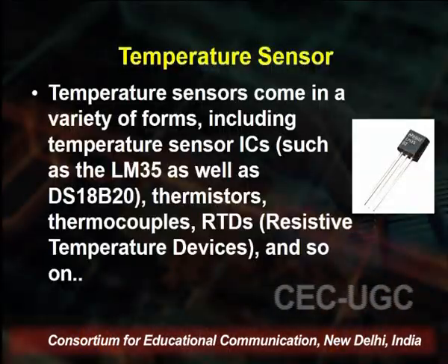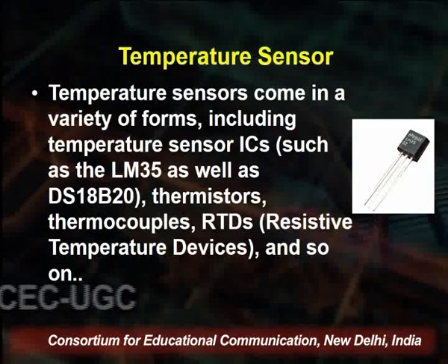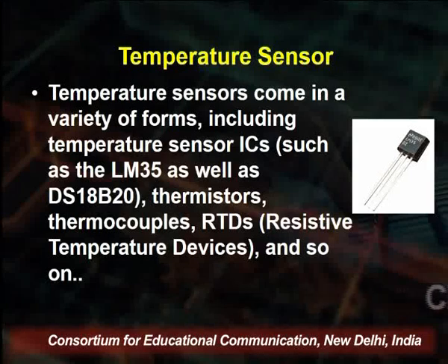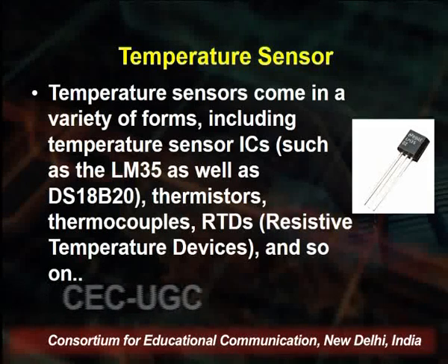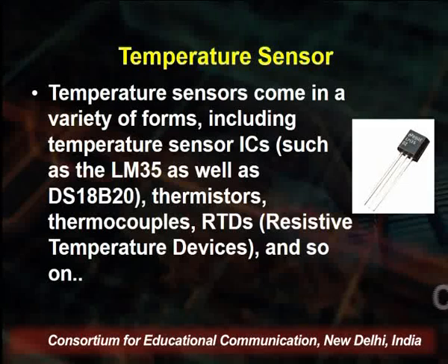This temperature sensor comes in a variety of forms, like sensor ICs such as LM35 as well as DS18B20, thermistors, thermocouples, RTDs (resistive temperature devices) and so on.